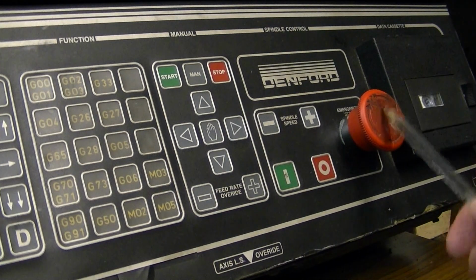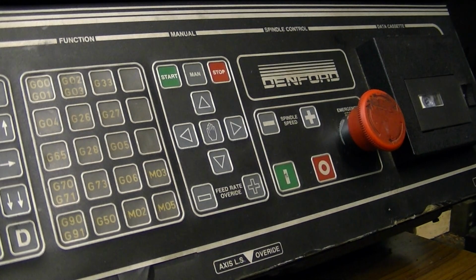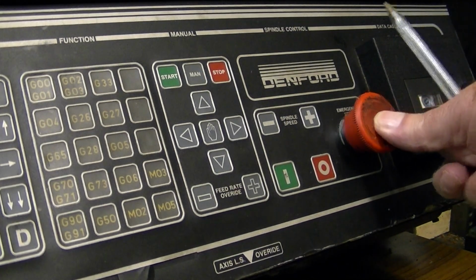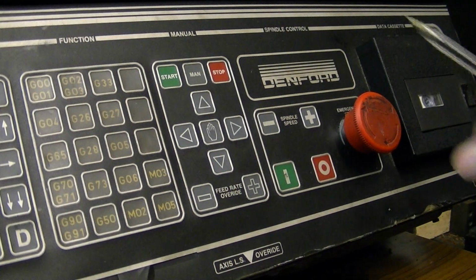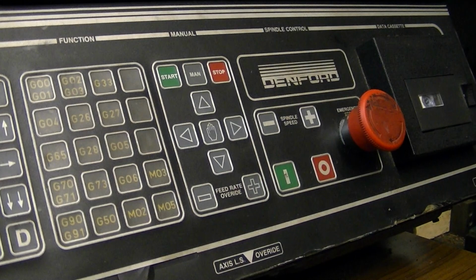And to the right of that you've got the stop switch, which is a lock off switch. Push it in and it locks it off, twist and it releases and it comes out. Enough said. Useful in an emergency, but if you do use it whilst you're running a program, it will stop the program and it will return to a manual operation when you reset, and you'll have lost your place in the program. So it would be necessary to manually move the turret to the correct position.